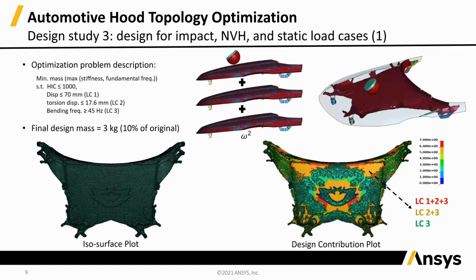This part is where we're showing how we can do multidisciplinary topology optimization. The disciplines required here are the impact, that head impact, statics, like I've shown before, and NVH, like the fundamental frequency. So in this case we've got just 3 load cases. And there's the design problem.